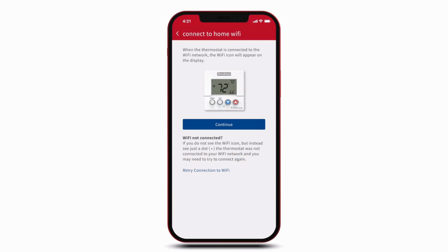This Wi-Fi authorization process authorizes remote access to the thermostat for 3.5 hours. It enables the installer to continue the commissioning process from their mobile device without the need to be close to the thermostat. If the installer needs more time, they can return to the thermostat and reconnect to the access point to gain an additional 3.5 hours of remote access.